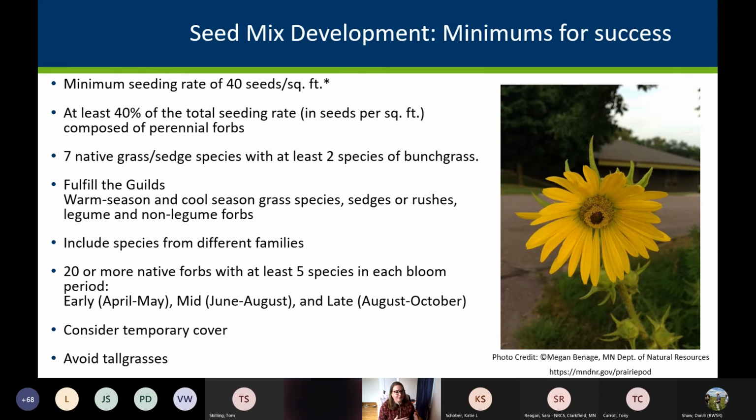The other thing that solar sites have to consider is that they're doing a lot of grading. They're doing construction of those panels. And so as they're doing the grading and construction of those panels, they need to make sure that they're not compacting the soil so much that they don't get any seed establishment. And we have seen a couple sites fail because the soils were too compacted. And that's pretty rare. And if you do a lot of prairie reconstruction, it's pretty rare to see things fail. I've only had 2 failures in my entire career, and one was because the seed was stolen and not planted, and the second was because we had herbicide carryover. So important things to consider.